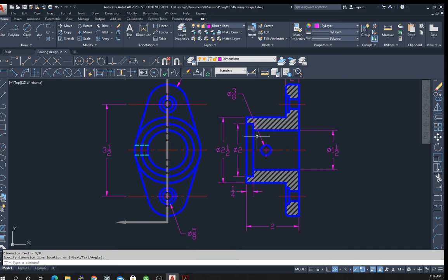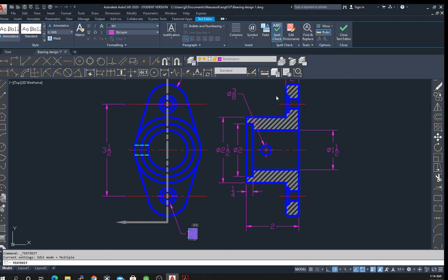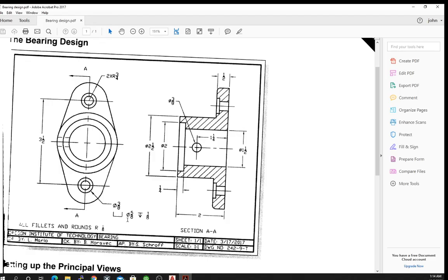Now, to locate the symbols, we should add here %%C3, actually not %%C, yeah, we should add 3/8 diameter, counterbore 5/8 with a depth of 1 inch.